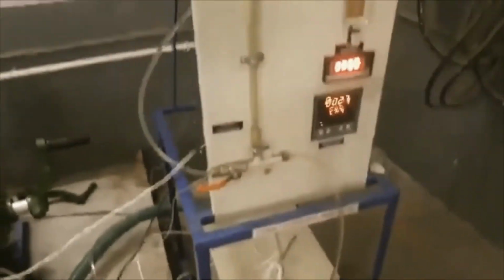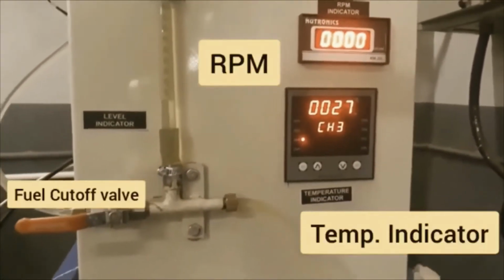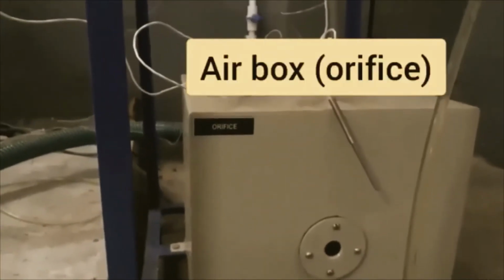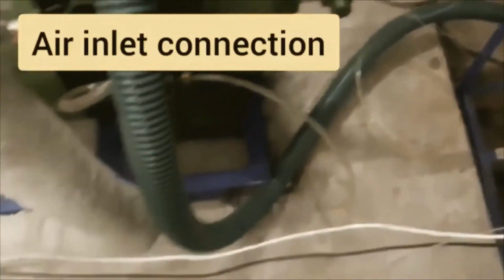Here you can see the test rig attached with the IC engine, which consists of the fuel tank, air box, and burette for fuel consumption. It also displays the temperature and RPM. You can see the air box for measuring the air consumption into the engine. The air is transferred to the engine from the air box with the help of the hose pipe. You can see this hose pipe.